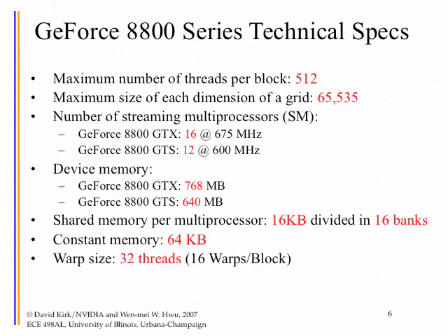So the product scaling is going to be the current generation. I'm going to be able to simultaneously execute, let's say, 10, 15 blocks out of the huge number that you specify. So it will take a while for the chip to go through them, right? And the next generation, they will add more function units, then they can simultaneously execute more blocks. So you specify a huge number of blocks, and they will generate products that will each generation be able to handle more and more of the blocks at the same time, and that's how they scale.